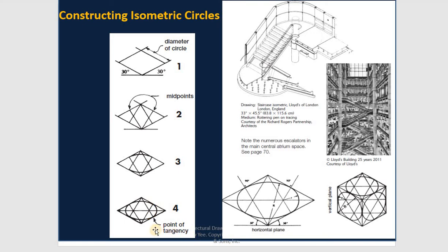So you have the point for the tangency, this one. And if you create the box like this, do the same thing. That means you start to have a trapezoid, and after that you create the midpoint from each of them, combine together with the top point, connect with the middle point, and you do all of the faces like this. Start with the curve between the middle points first, this one first, and after that go with the other curve.